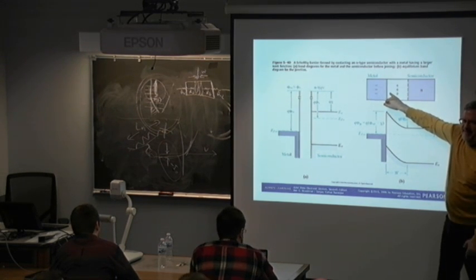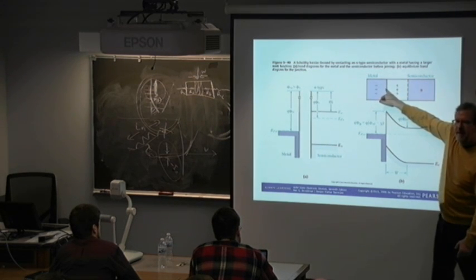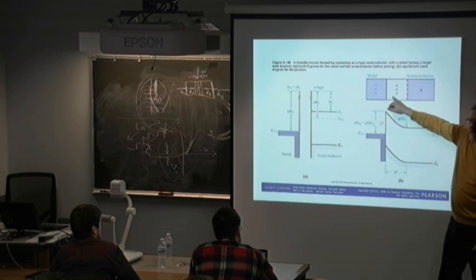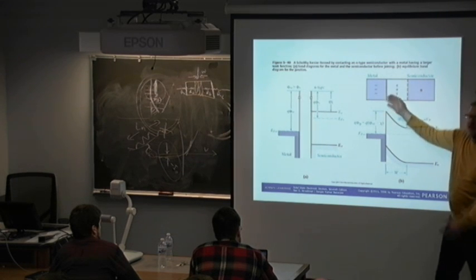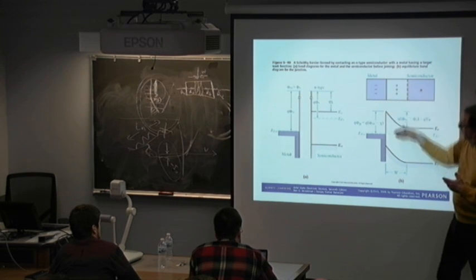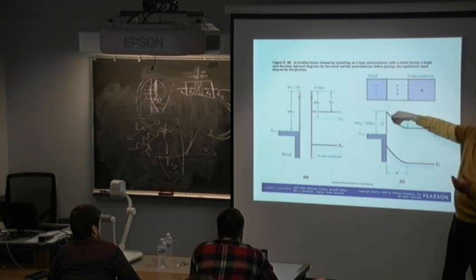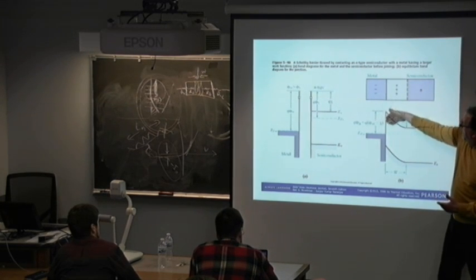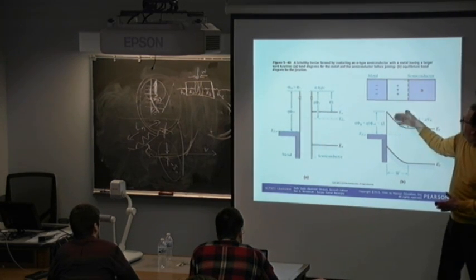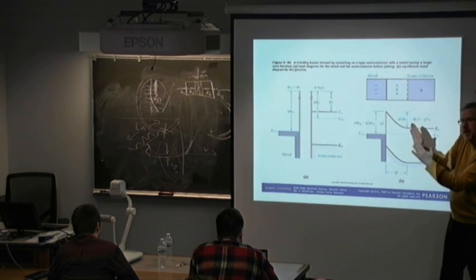Is it intrinsic? No, not intrinsic. On the right track. It's depletion. So this is the ionized donors, right? It's the depletion region. So the band bending is always representative of charge and electric field, right? So if it's tilting, it's electric field. If it's bending, there's charge.